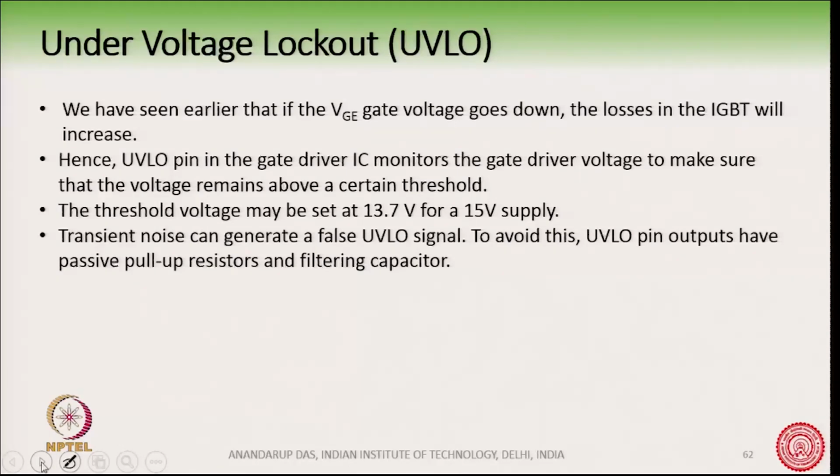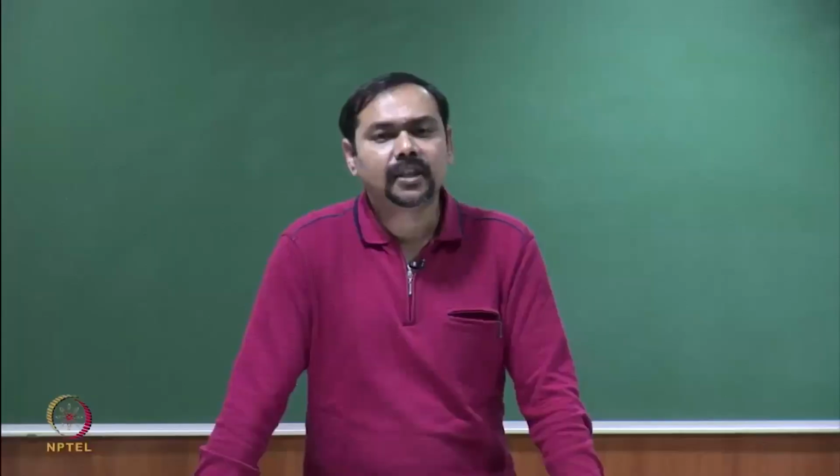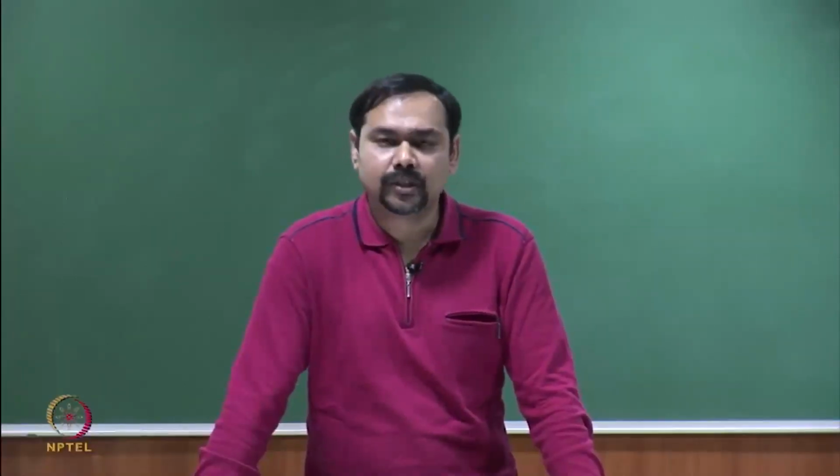The losses will increase and also the conduction loss will increase. So, there is always an under voltage lockout pin in the gate driver IC that monitors the gate emitter voltage.